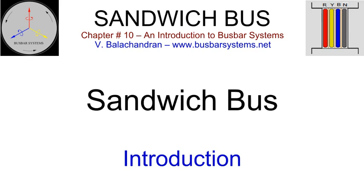Presently, sandwich bus construction is limited to low-voltage applications in AC and DC systems. There are low and medium voltage cast resin bus, where the thickness of the resin insulation is significant. The main advantages of the busway over bus duct are as follows. Extremely compact. The cross-sectional area is reduced to approximately 15% of the equivalent bus duct. Low inductive reactance and hence low voltage drop.